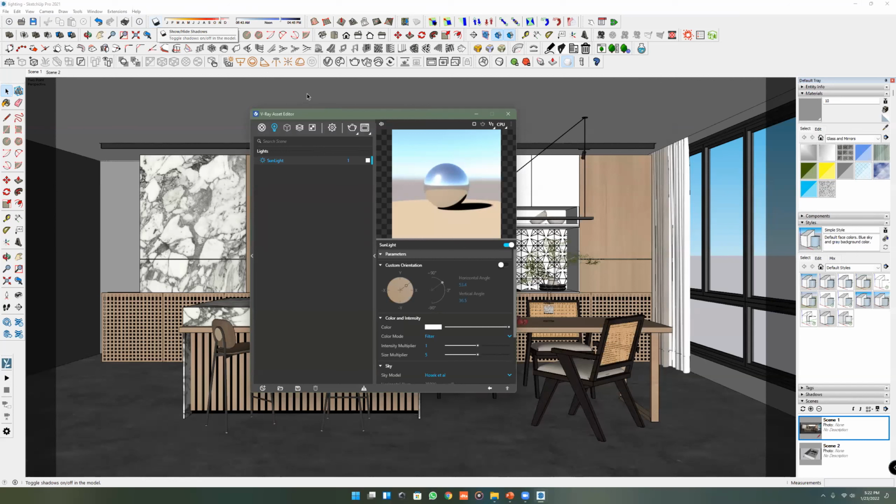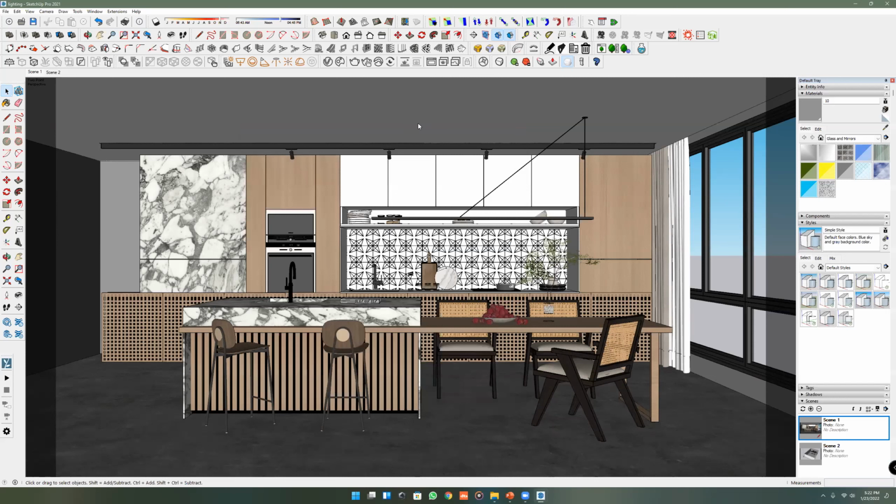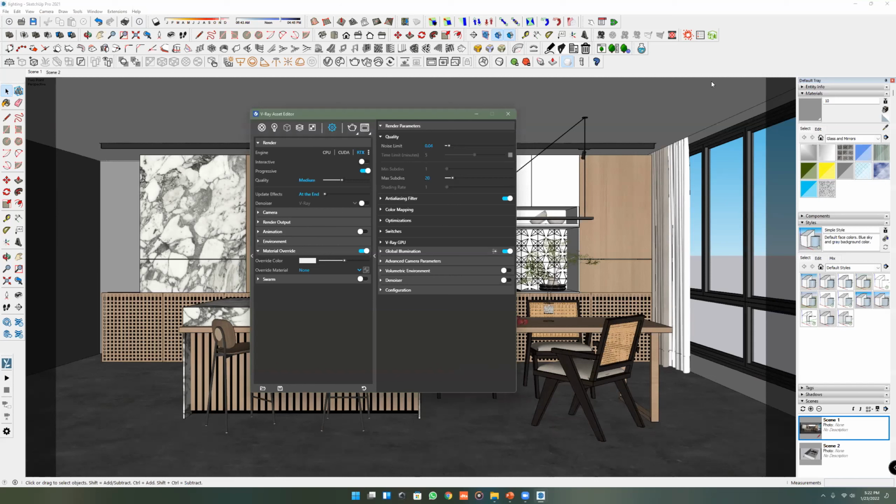And we 3D artists have a common practice, a technique or a stage before doing the light balance. We do a material override render. Don't get bothered by what that means. It's going to take all the materials out and render in just plain white. So I'll quickly go through a sample render and show you how this clay render, or material override render, works.